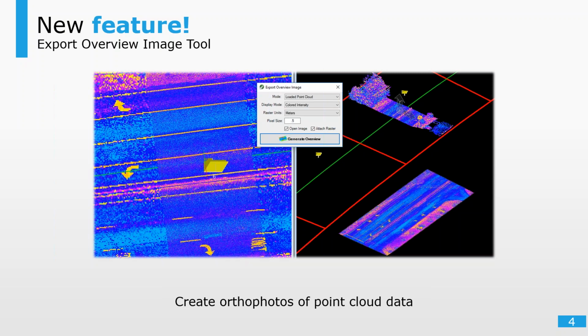And that's very useful. You can take those photos and pass them on to engineers and people that may not want to see a point cloud, but you can pull them in as rasters, and do 2D measurements, compare them to plan views, compare them to your model, outside of the point cloud realm. Nobody has to have a point cloud for that. So we can export these images. Very powerful. We can see the usefulness of that. If you're trying to talk to your engineers, or give your customers something with not much processing involved, just export this, and they can look at the lines themselves. So it's pretty powerful.